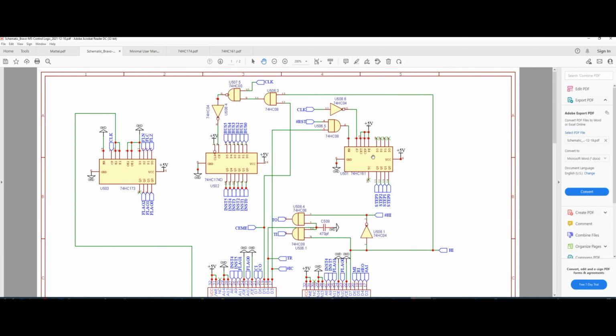And then the rest of the pins are quite clear. As you can see, the chip enable and the count enable are actually tied to high. That means that we are not reading anything from the input side, and also we will be continuously counting. However, an interesting thing about this chip is that the master reset line, which is an active low signal on this chip, is actually coming from an AND gate. And that AND gate is fed with 2 other signals, which we're going to talk about right now.